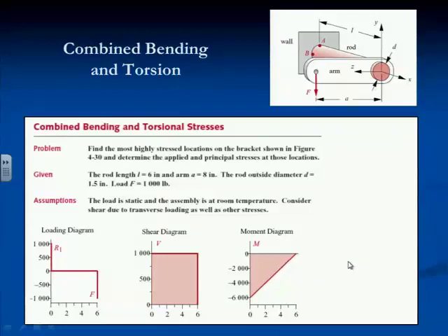So an upward, a positive shear gives me a negative moment because of the funny sign conventions. So this time I got smart and I'm walking this way. So I see a little bit of area, then a little more, a little more, a little more, a little more. And this is the value of the areas, because when I finally get to the wall, I've got all the area accumulated and got my biggest moment at the wall, right?